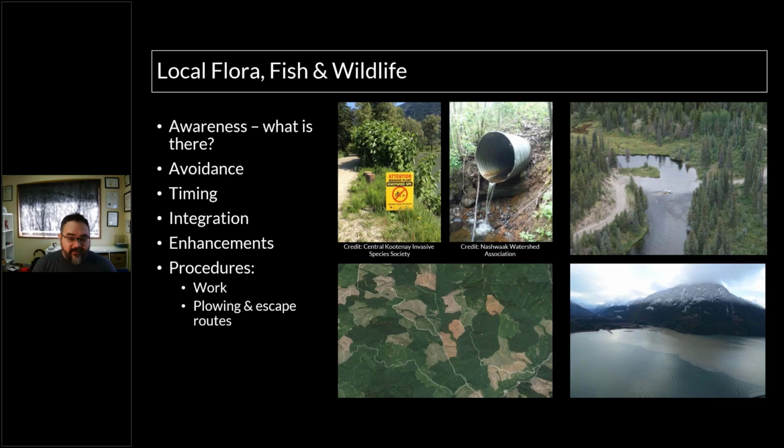So we've been putting in these embedded rounds, or simulated streambed embedded rounds, where we have gravel inside the culvert, so we can still have the natural passing of bed load, but we're able to put in a culvert. It gives us flexibility of grading across, having the road grades go right across a stream, or having it in a tight corner where, for a bridge, we'd need straight areas on each side.